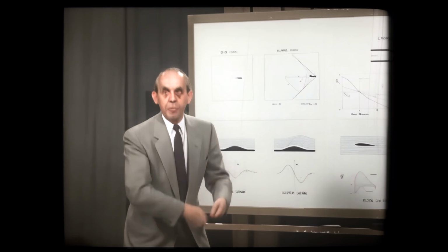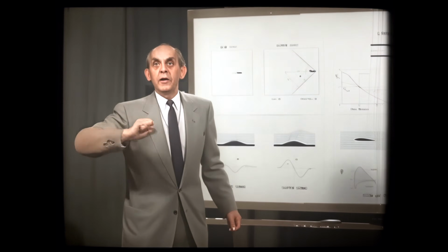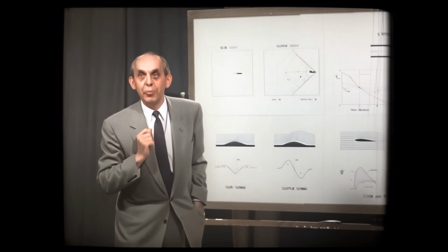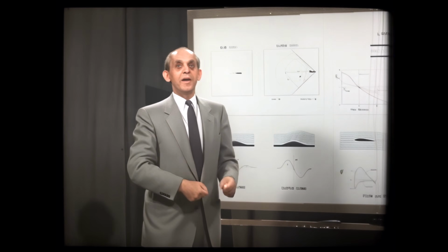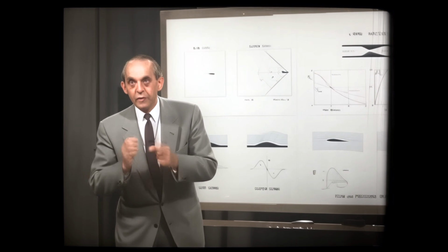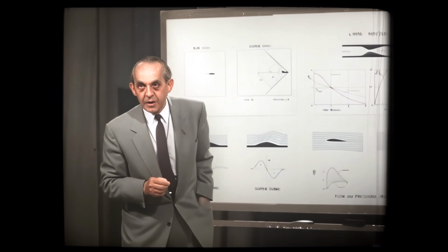And the more you pressurize the air in this vessel, the higher the speed will be. Yeah, up to a certain point. You will find out that you pump it up as much as you want and you don't get out of this opening more than the speed of sound.